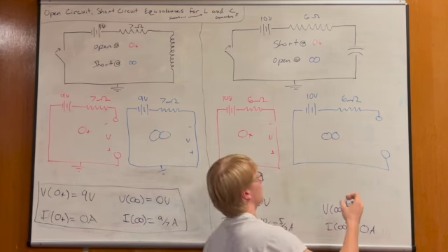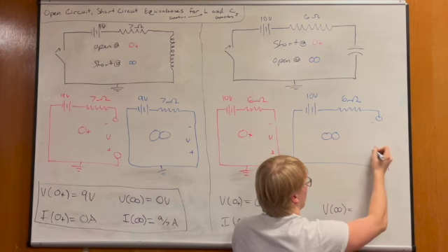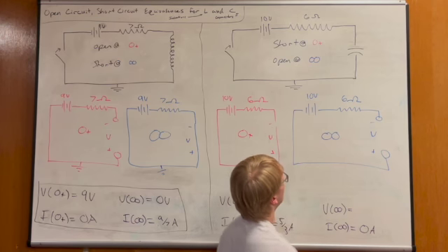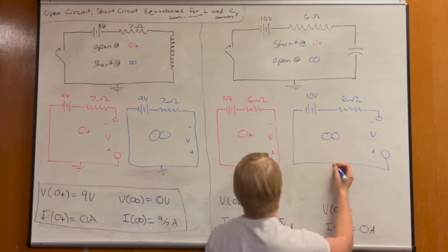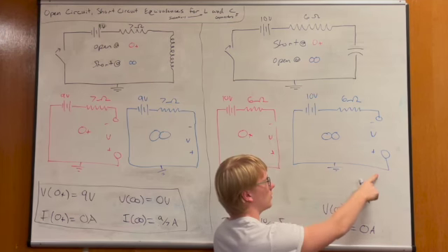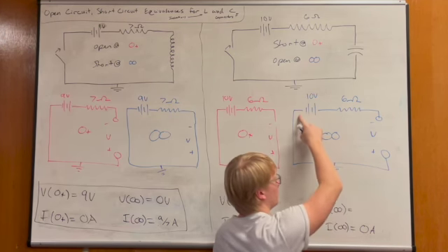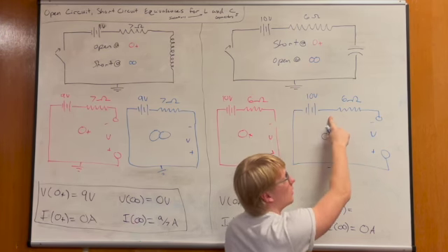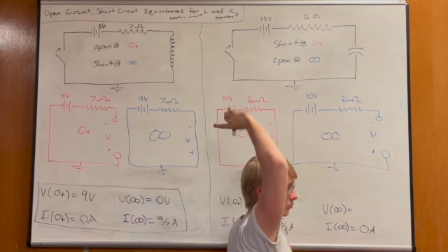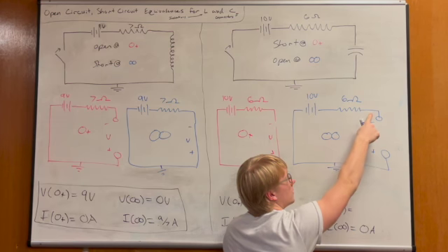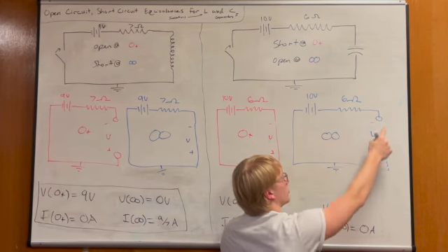And so over here, we can have a voltage jump because they're different nodes. This node right here is just like our first one. This node right here is the ground, all the way up to here. And we're going to say it's 0, which means this one right here is 10. Which means this one right here, just like what we proved over there with voltage division, is also 10. So this node is 10, this node is 0, which means the voltage jump is 10.